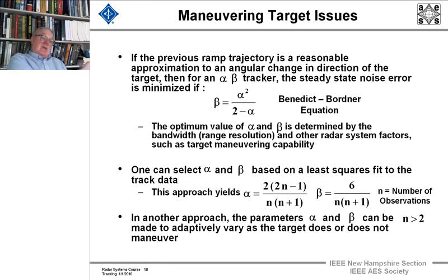If it's a half a G turn, you'll see it slowly coming and you'll track it easily around it. But if it's a very fast 3G turn that's at a limit, then you're going to have some trouble with the state vector that you predict not being exact.